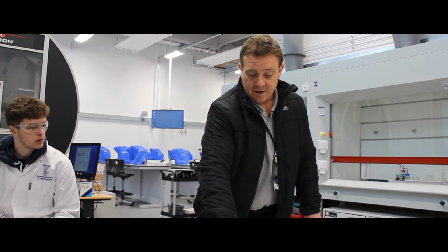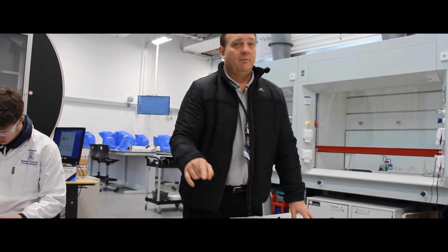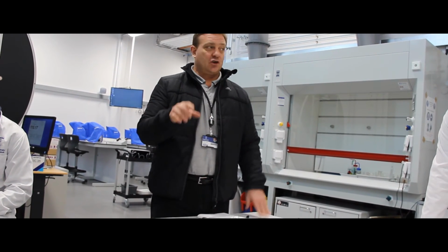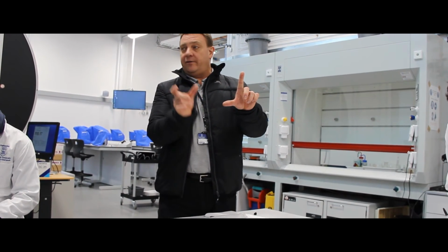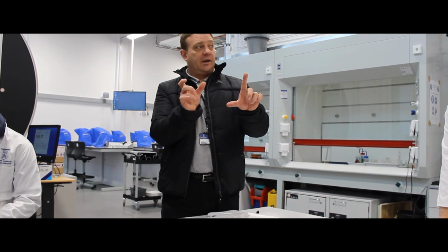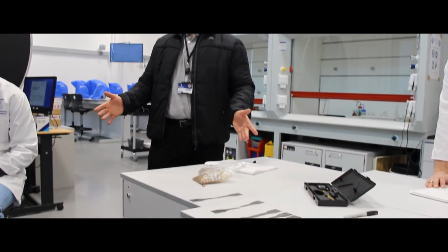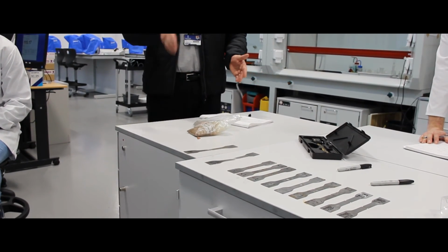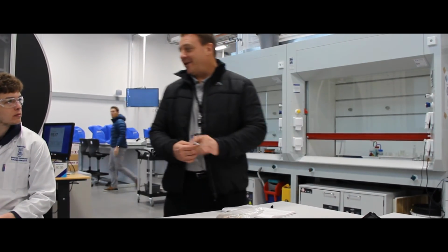One point to note is that the gauge length is important to be able to determine the elongation. Even if you don't get that strain, because you have a true stress, true strain curve there, the strain is dependent upon the definition of your initial gauge length. So I used 70 millimeters, but mine is slightly out. I'm getting a 20 millimeter displacement at the ultimate tensile breaking point, whereas actually you get about 30 millimeters. So I did something slightly different. Whether you can correct that or not, that's the icing on the cake.